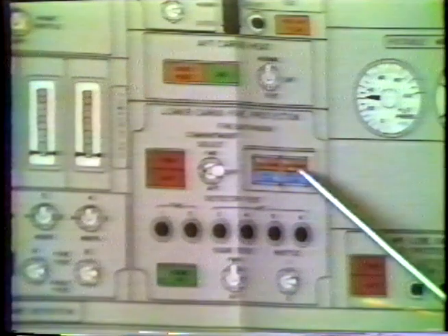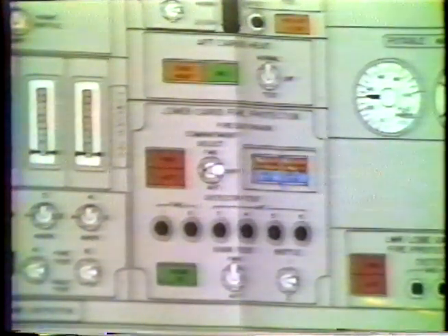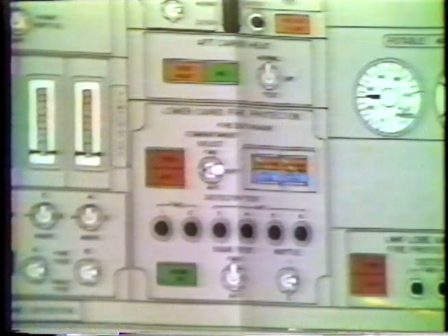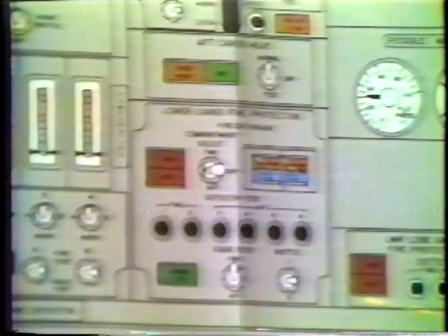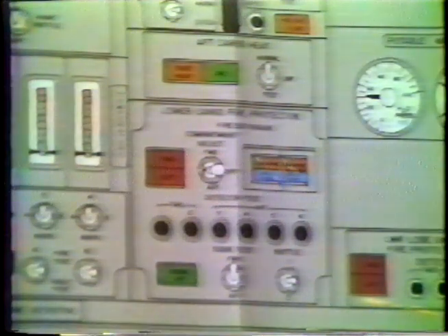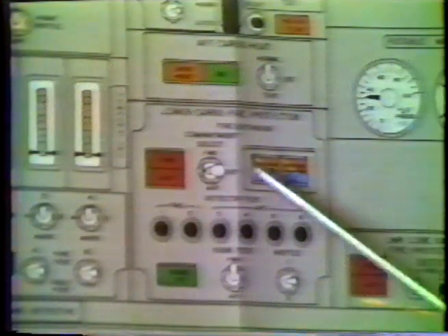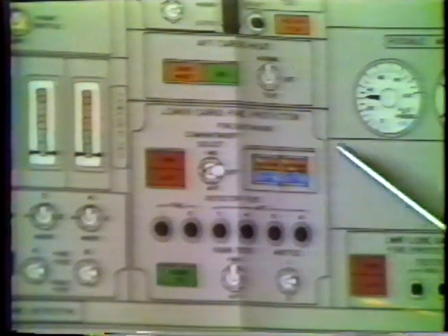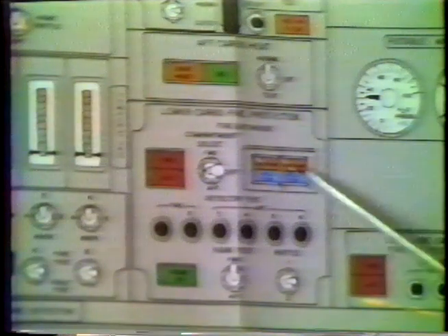The second bottle is a much smaller bottle, and upon an hour of operation, after firing the first bottle, it will bring the concentration of Freon up to approximately what it was when the first bottle was fired. The second bottle may not be sufficient to put a fire out if you fire it first. Because of that, there is a double guard here. First you have to lift up one to get to the first bottle, and then you have to lift up the second one to get to the second bottle.